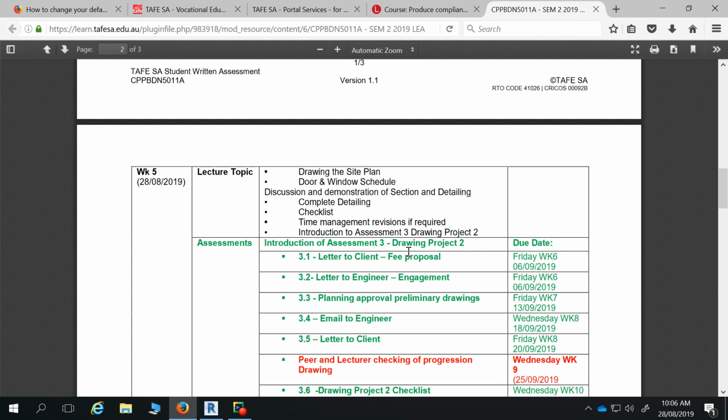Why you need to have all the glazing is obviously for your assessment in energy rating, if you're going to get it done like that, or if you're going to do your deemed to satisfy and use a glazing calculator, then you need that information on your schedule so someone can find out what you're using. We're not going to do the glazing calculator. We're going to assume that this is just done by an assessor at another stage, etc.